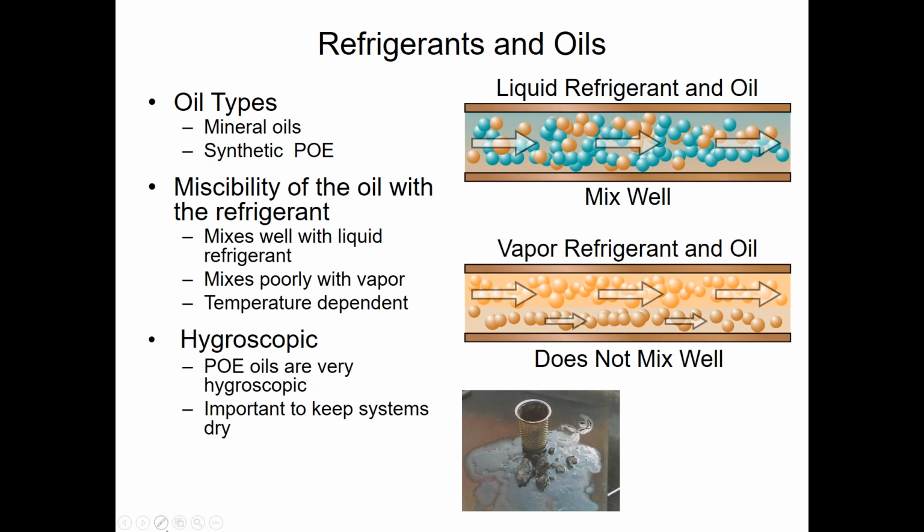Just remember our vapor lines are the ones we really need to look close at. Liquid lines, we want to keep them as short as possible, of course, and we want them to be sized correctly, because undersized piping can cause capacity loss on all three lines, your liquid, suction, or discharge. And on our vapor pipes we want to make sure they're not oversized, which would slow the velocity down of the refrigerant and we'd lose the entrainment of the oil. So pipe sizing is very critical.